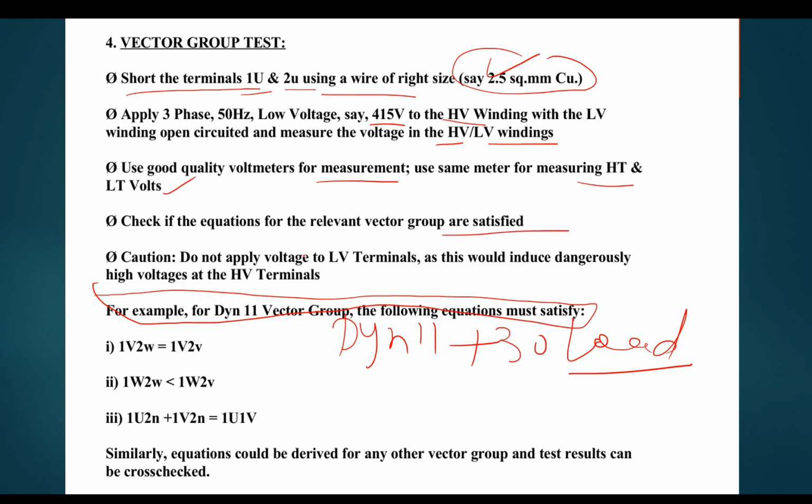Do not apply voltage to the LV terminals, as this would induce dangerously high voltage at the HV terminals.